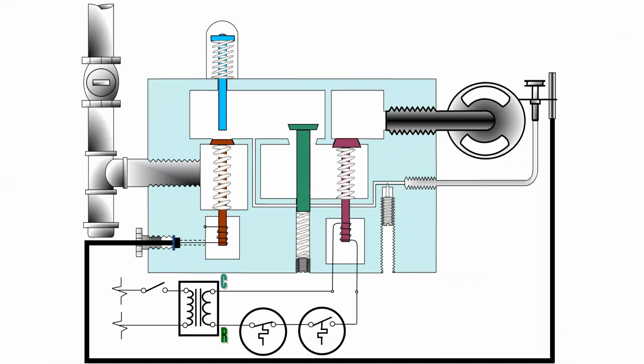If we were to look at the entire system with the flow of gas and the operation of the thermostat, it would look somewhat like this. What we have is a main gas rigid steel pipe that's bringing natural gas to the main gas valve. We then also have a thermocouple connection. The thermocouple is threaded into the main gas valve, into the power unit, and it will energize this small electromagnet. The thermocouple is the black line along the bottom of the screen, which then ends here beside the pilot burner. The pilot burner is supplied gas through this small line all the way through to this chamber.